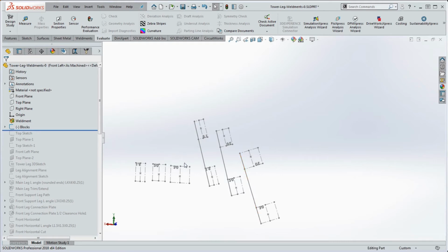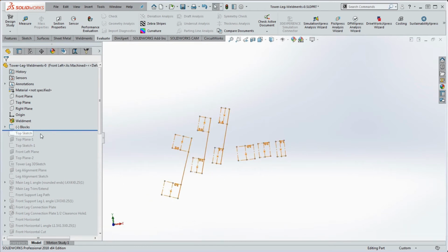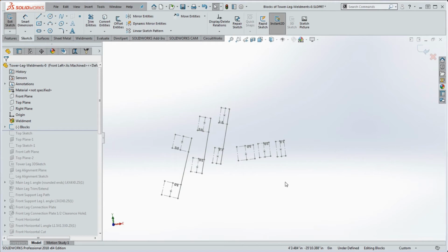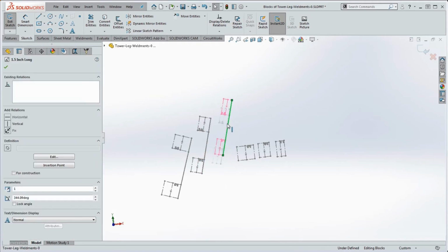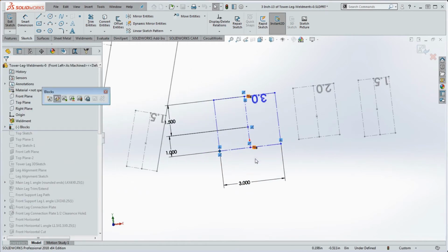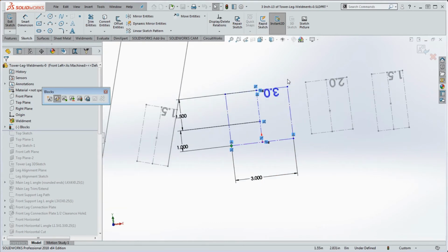So let's go ahead and turn that around a little bit so we're actually looking at it front to front, and let's go into that sketch and edit it. So if we right click on it, go to Edit Sketch. Now you can see a very dramatic change in here, which really didn't happen, because it's still gray. And sketch blocks are kind of like sketches within sketches. Even though we're inside of a sketch, we can make modifications to the sketch, like moving these sketch blocks around. We really don't see anything as being blue. So we can go inside these sketch blocks themselves, like maybe this 3-inch sketch block, and see what makes up that sketch block. As I mentioned before, we have our pass segment line, which is going to come down on this side, and then that's going to define where the spine of that structural member is going to be.